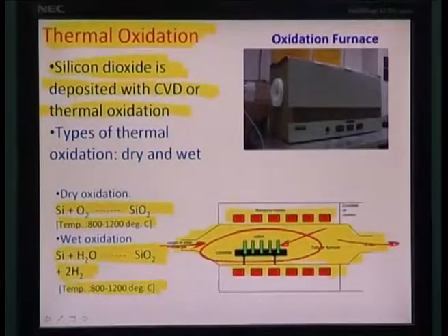As you heat this wafer to a certain temperature, there is always thermal motion or movement of the atoms on the surface, and then you flow oxygen. So there is a rapid capture of oxygen moieties over the whole surface, which finally develops the oxide. There are different models to explain the different growth kinetics of oxide, which I am not going to look into at this time. We are towards the end of this lecture.